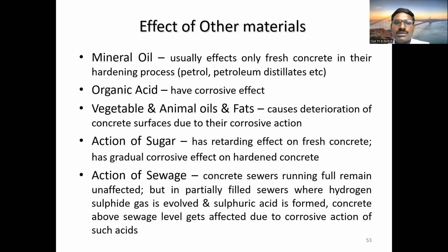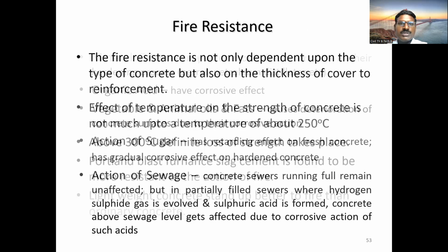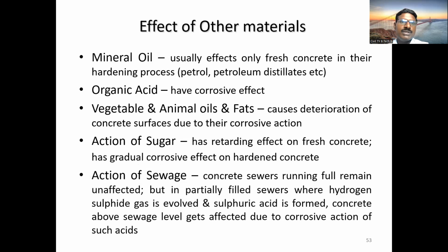a gradual corrosive effect. Then action of sewage. Concrete sewers running full remain unaffected, but in a partially filled sewer where hydrogen sulfide gas is involved and sulfuric acid is formed, concrete is attacked. So this is up to the effect of the other material.